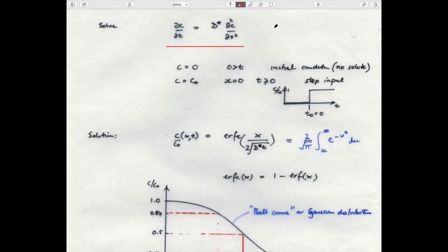And so if we do have this system that we're talking about, which is upstream to downstream flow driven by Darcy flow and advective flow, then what we'd like to be able to say is what is the concentration as a function of time, maybe at this location, some compliance location where we're standing.